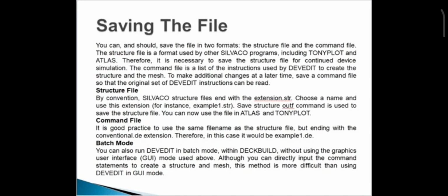You can and should save the file in two formats: the structure file and the command file. The structure file is a format used by other Silvaco programs, including Tonyplot and Atlas. Therefore, it is necessary to save the structure file for continued device simulation. The command file is a list of the instructions used by the DevEdit to create the structure and the mesh. To make additional changes at a later time, save a command file so that the original set of DevEdit instructions can be read.